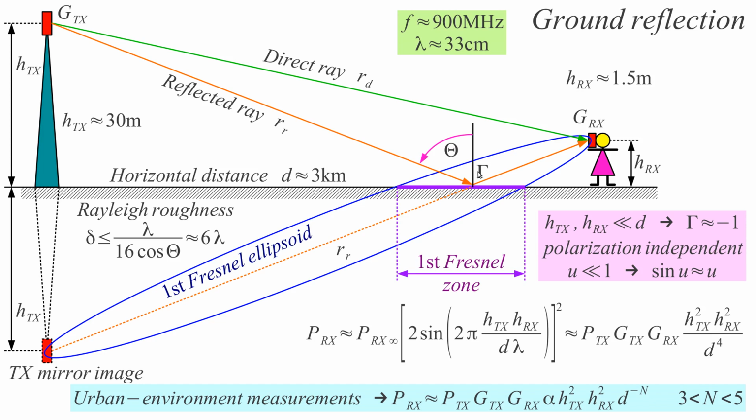If I take the typical values for a GSM phone, 30 meters tower height, 3 kilometers horizontal range, and pedestrian height 1.5 meters, so the pedestrian usually keeps the phone on his or her ear, this is 1.5 meters above ground. I have quite a strong reflection off the ground.